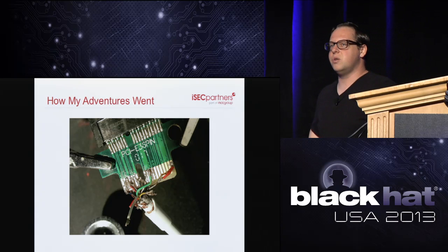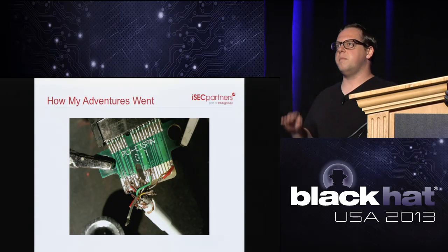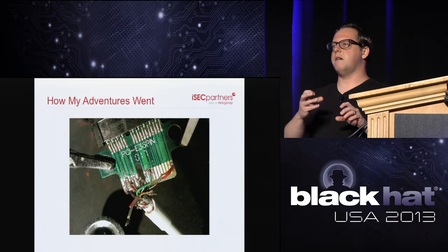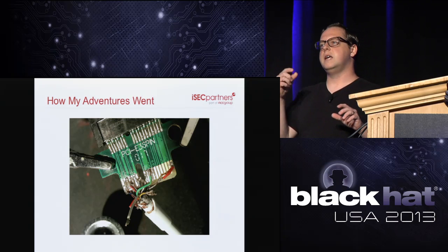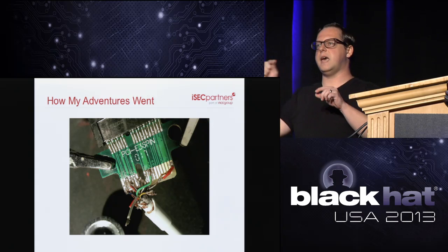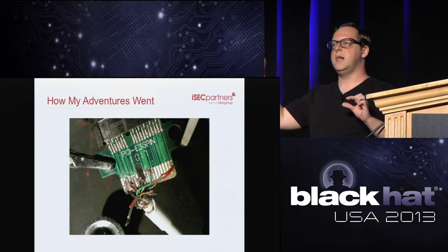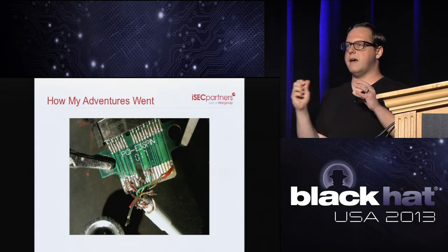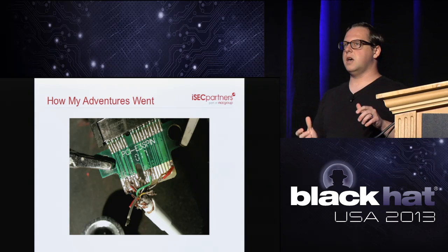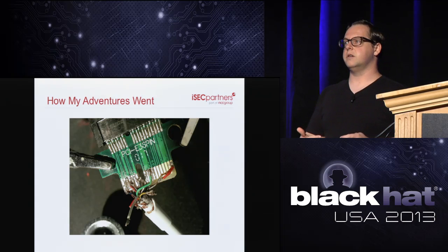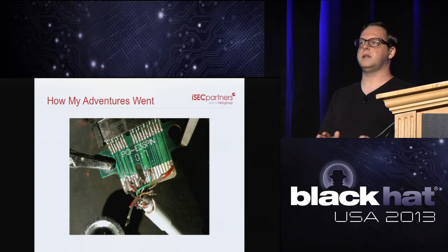These wires are so small. The PCI Express wires that come out, there's a jacket, and if you pull that jacket off, there's ground wires wrapping around it, and then within there's another wire with a jacket, and then within that, there's the actual PCI Express wire. To strip that first jacket, I used the grooves of a pair of needle nose pliers, and that fit perfectly.